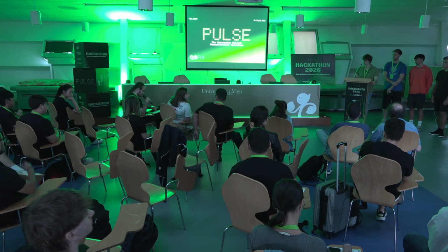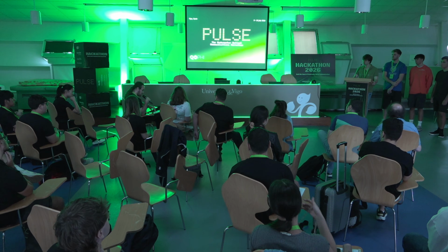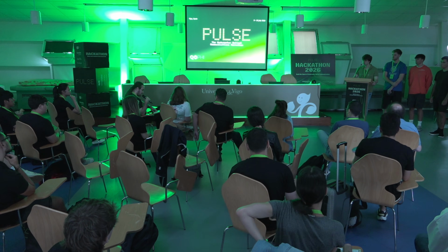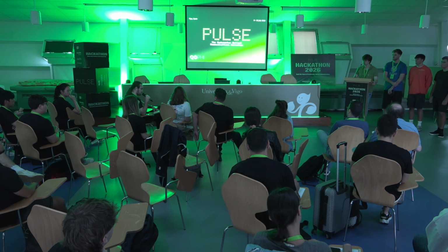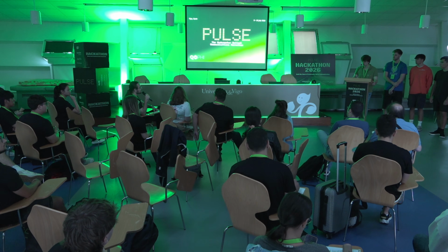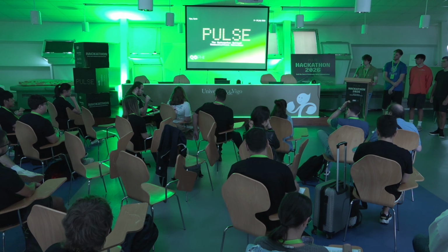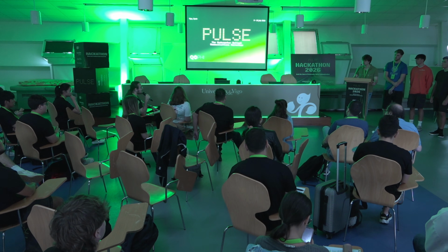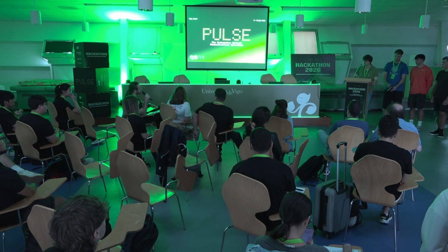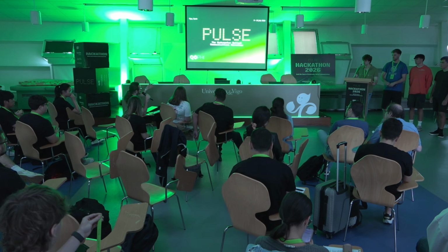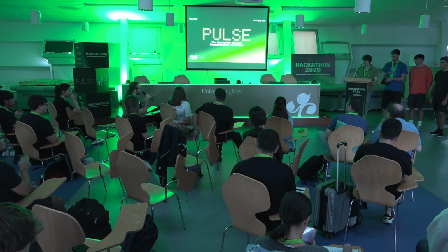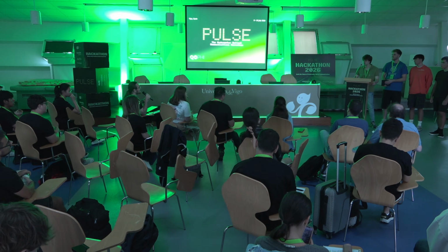The hardware that you chose is fine, but I have a question. You use a transimpedance amplifier, and you say that it has an 80 megahertz gain bandwidth product. Yes. And you use a transimpedance of 10 kilo ohms. Yes. So that gives you 8 kilohertz bandwidth. So the simulations that you have are really not optimal, not even comparable with the hardware that you have. I mean, you have 8 kilohertz. My voice has more bandwidth right now than the channel that you have.